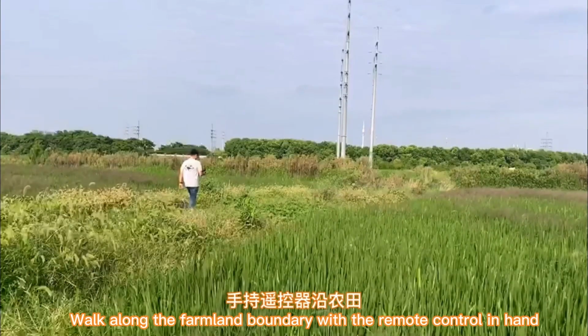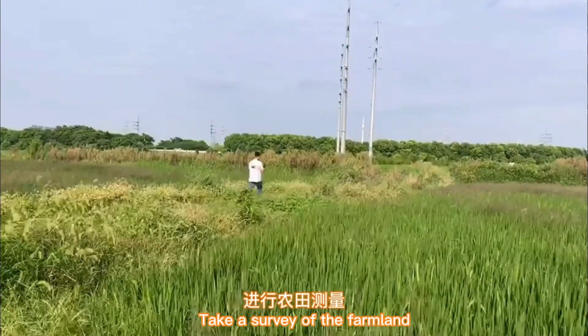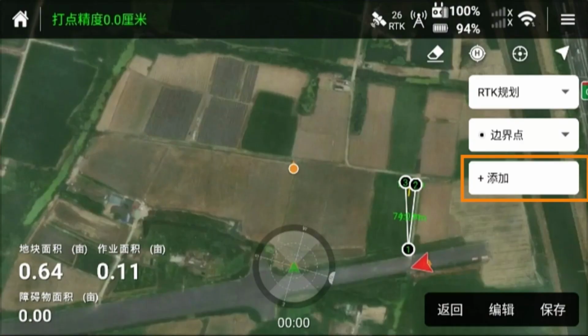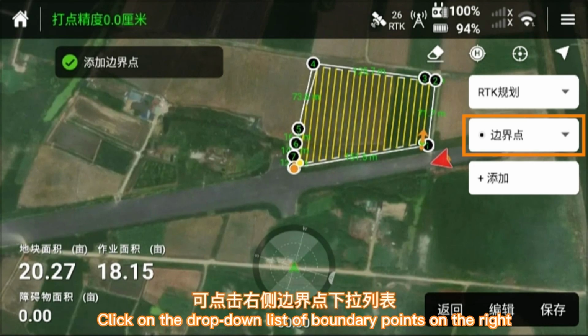Walk along the farmland boundary with the remote control in hand. Take a survey of the farmland. At each corner of the field, click to add a line point. If there is an obstacle in the working area, click on the drop-down list of boundary points on the right.